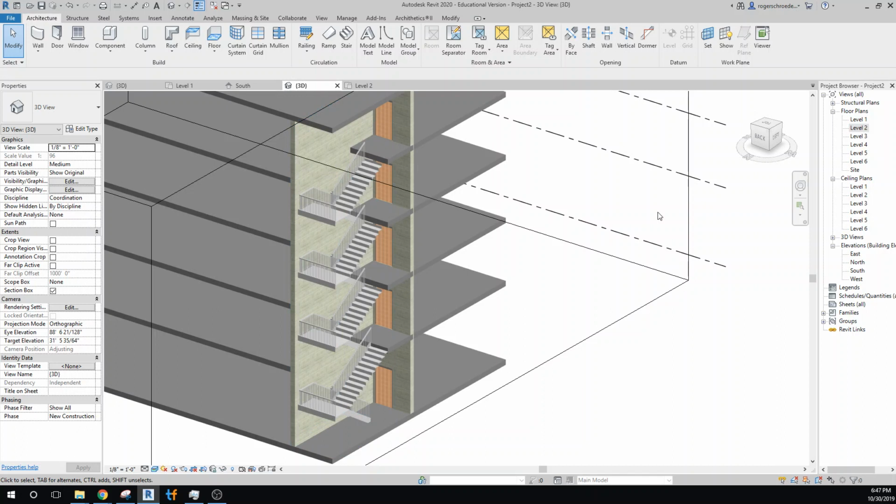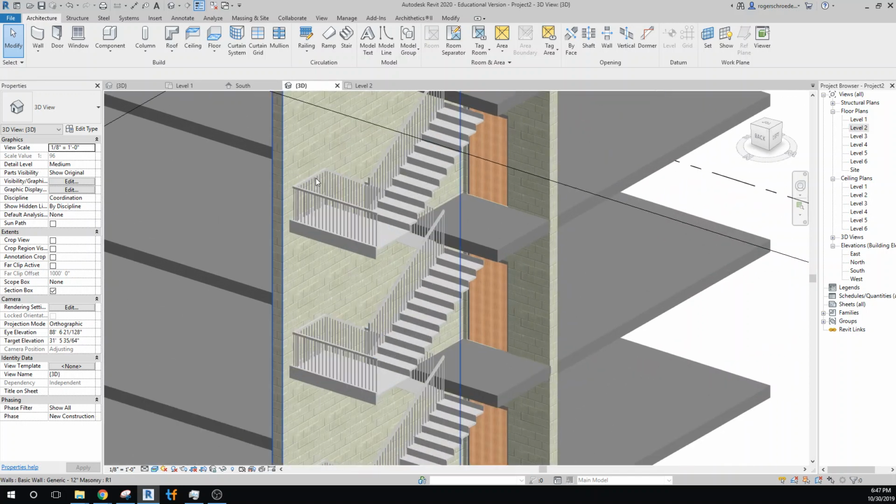Let's now take a look at, and I'm seeing some other issues as I continue to talk. The railing returns are all right, except we don't really need railings along these surfaces. We really need handrails. So all kinds of BIM issues, but for the few minutes that you work on a drawing like this, it really is surprising how much can be completed. And I'm also seeing a little bit of an error in the way the stairways are not hitting the landings properly.